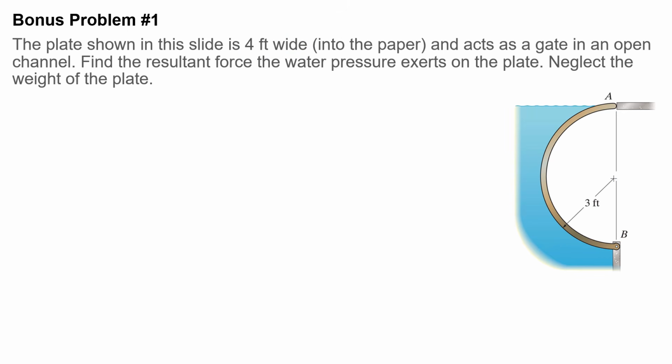All right, now we are going to calculate vertical force. And to do that, what I'm going to do is simply name some of the critical points that I am going to work with. So this point, I'm going to call this C. Okay, now if I ask you what would be the vertical force, you would tell me that this gate consists of two parts, part AC and part CB.